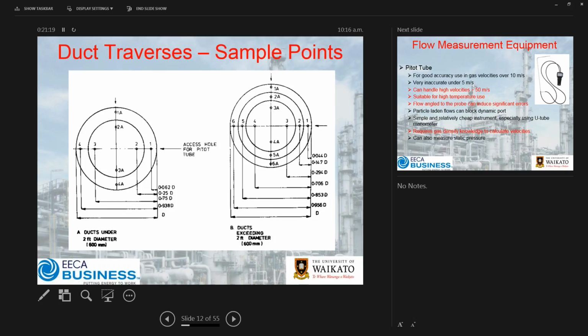And people sometimes don't even bother with doing that, and they just either do vertically or horizontally, which in the grand scheme of things, depending on the nature of your upstream flow condition, that's probably adequate. And so what you'll find is that you'll get an approximation. So that's all part of the providers that provide those annubars. That's all set up as part of their standard reference points for that annubar, and so that'll all be derived,